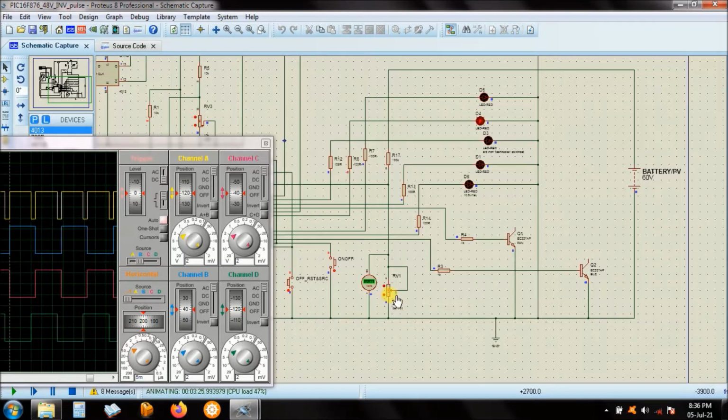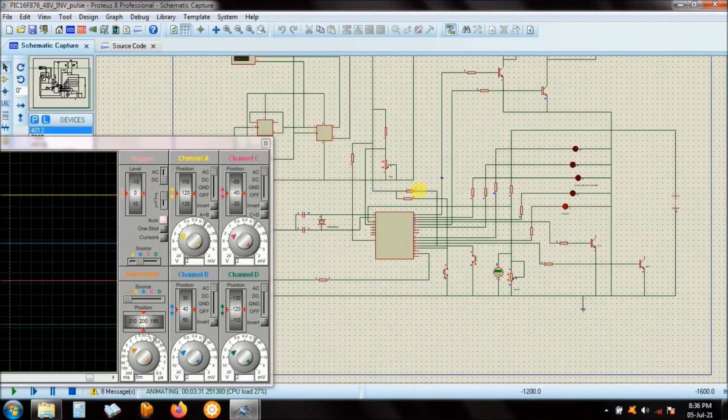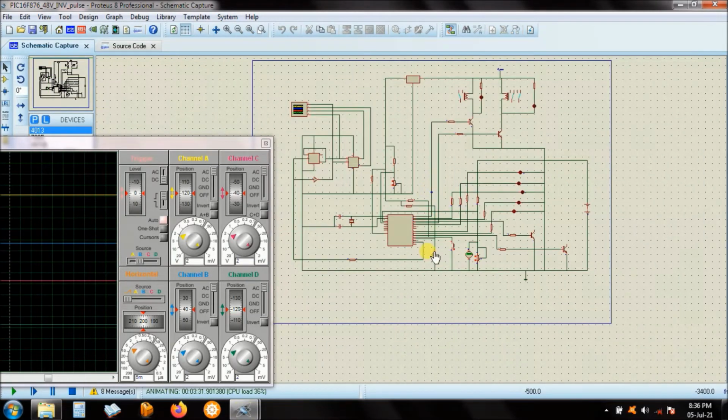I think somewhere below there it will switch to alarm mode because it has gone below 30 volts, by design. That I fixed. Okay, so that's alarm mode. When it gets into that, it is off, and you have to reset it using this button